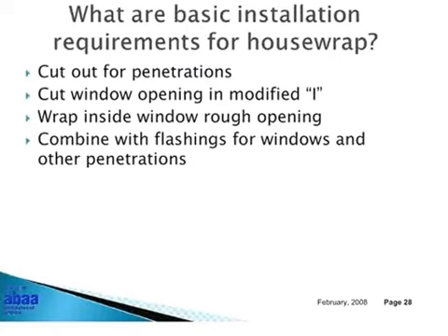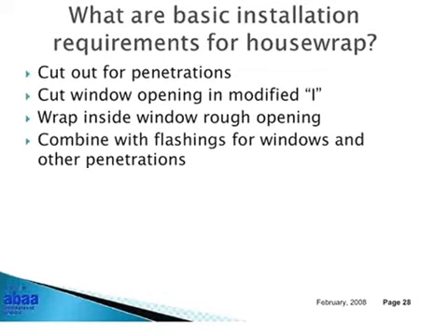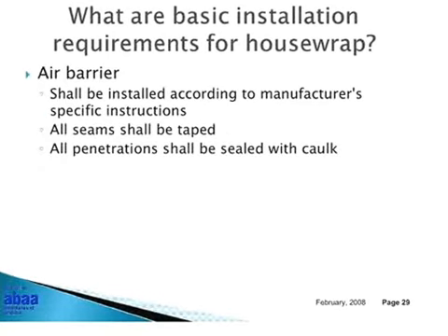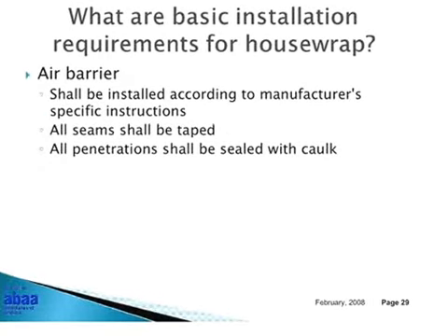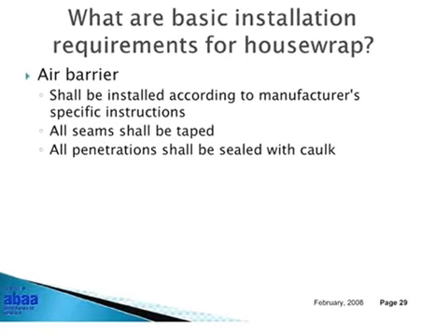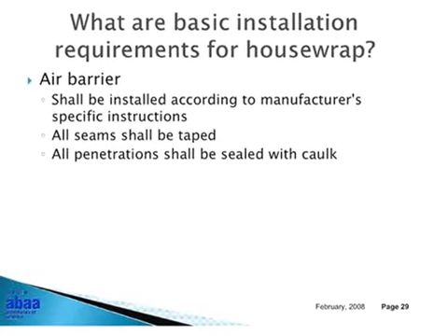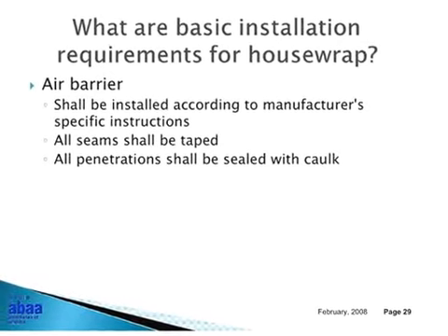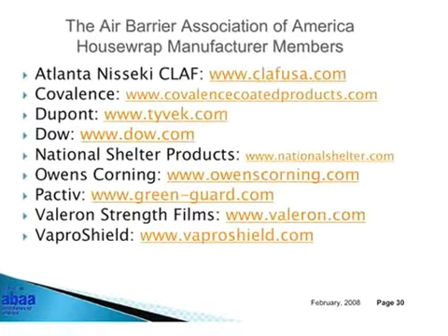When you come to a window, you want to use the inverted Y method, where basically you cut the material and then fold it around the window opening and fasten it in place. You're also required by code to integrate the water-resistant barrier, or the house wrap material, with your flashing materials. This is a very key component so that you're tying the house wrap, the window, and the flashings all together, and again, making sure that everything is shingled to the outside.